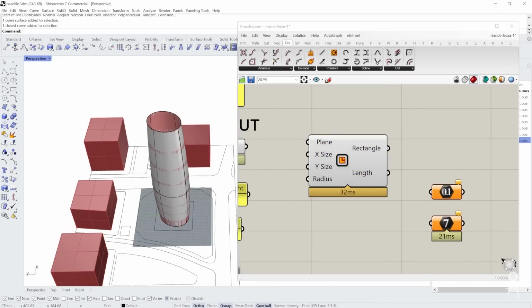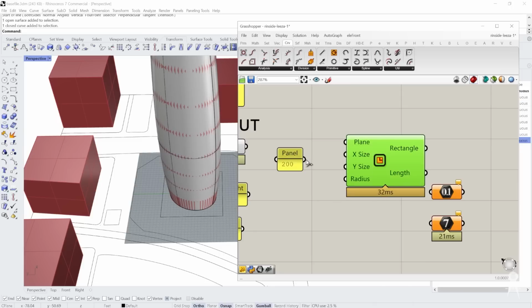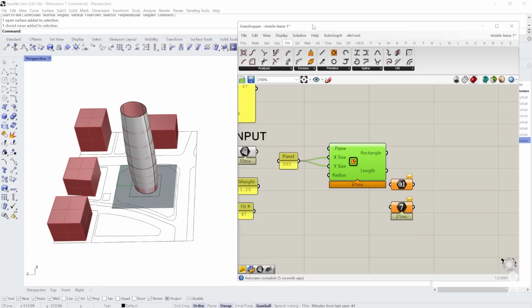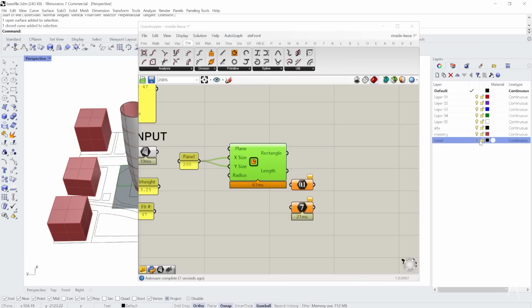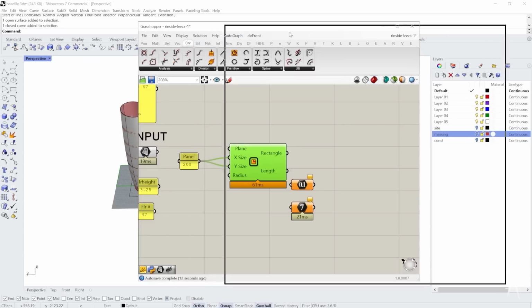As you can see in the file, it's not really known, but we know this is about 100, and I just need it bigger than the size here. So I'm just going to do 200 by 200, and since I started at the origin, it should be fine. I'll just check what that is, and I'm going to turn off my site. I don't need the site or massing for this part of our exercise.